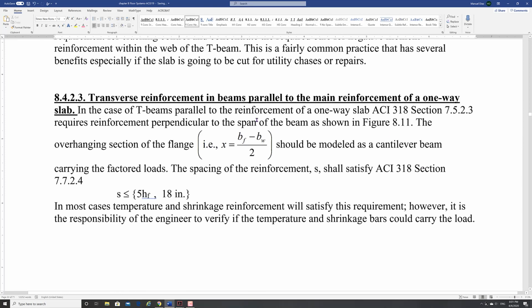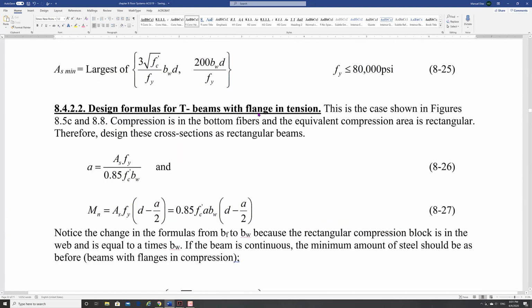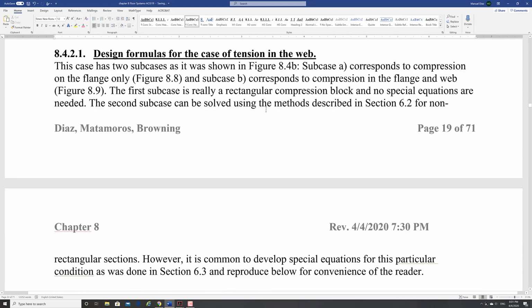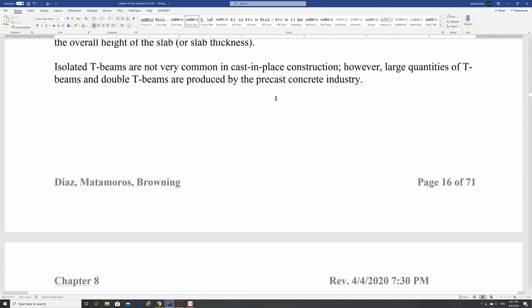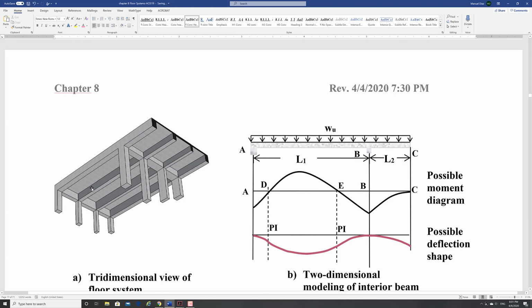And this one right here is, remember I mentioned that on the beams, you go back to this figure that we have here. We're doing the design of these right here. And when you do your slab, you design this way, and you're putting bars here on the top, but you're not putting any bars on the top of these beams due to the slab.